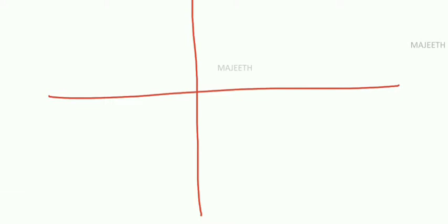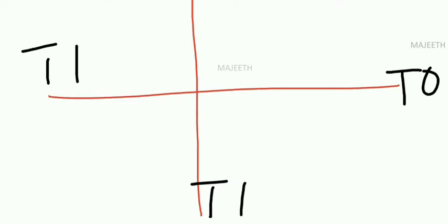Right, we know that the polar plot has the general form like this. It will always start from the type. So this is talking about type 0, this is talking about type 1 of the system, this is talking about type 2. Sorry, this is type 2, type 3 of the system. These are all starting points of the polar plot, whereas the endpoint is determined by order.